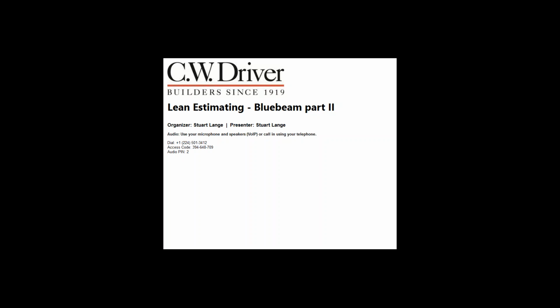Okay. So next step. Anybody? The page labels. Yep. So now we made sure they're all correct, all of the sheet titles. So now we're going to transfer those to the page labels. So you click on the thumbnail view up here, which is the little 4 squares next to the bookmark tab. And then we click on Create Page Labels, which has the little star thing there. And we're going to create it from bookmarks. Hit OK.